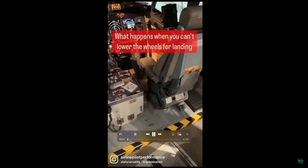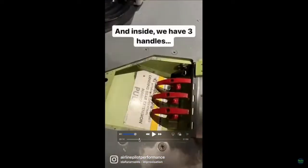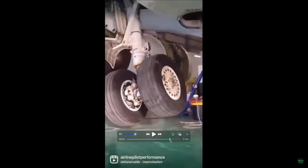Because like I mentioned, the landing gear is really just potentially gravity fed. There's a way to be able to actuate it even without the systems. There's a little manual door release here behind the pilots that you can pull. And these are cable driven, and you can actually extend the nose landing gear and the left and right sides of the main landing gear, all without hydraulic pressure. That's again because it's gravity fed, and all you have to do is release it and let gravity do the rest.